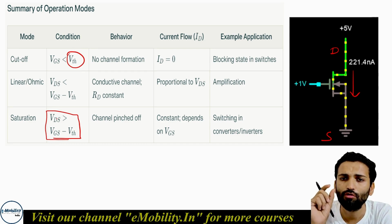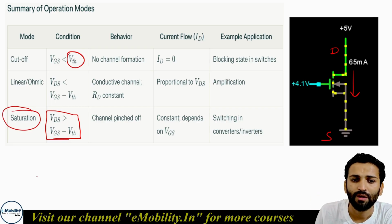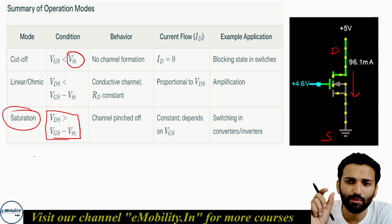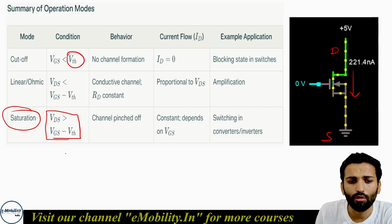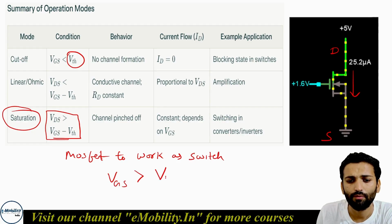This is the condition which allows the channel to build fully. That means for switching purposes, we have to keep the MOSFET in saturation. So one thing you should learn from here is that for a MOSFET to work as a switch, V gate to source should be more than V threshold.